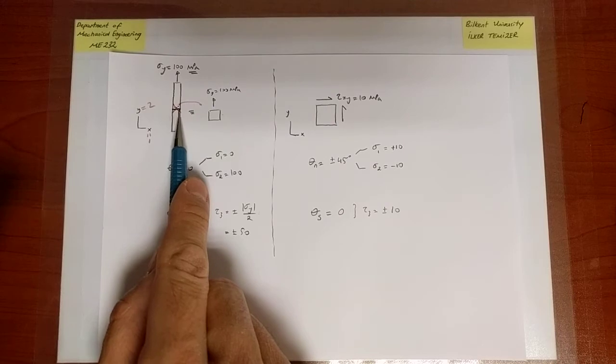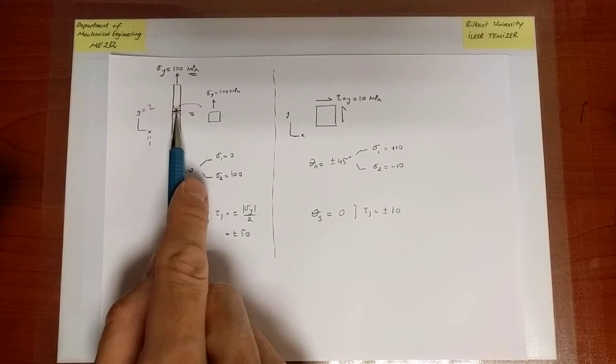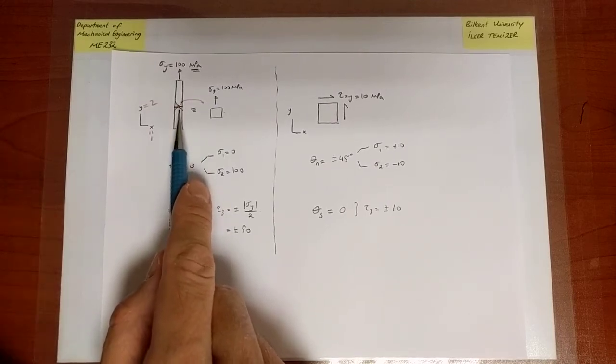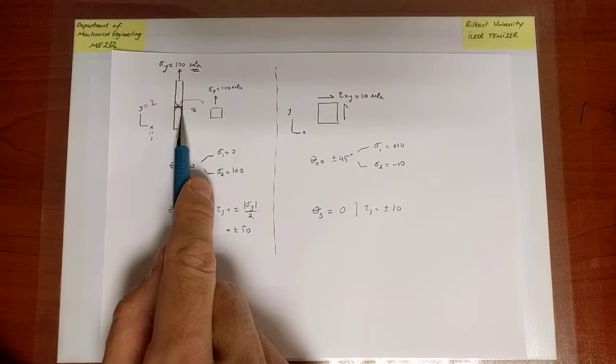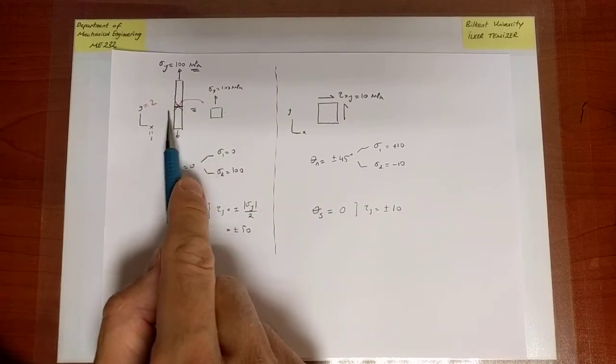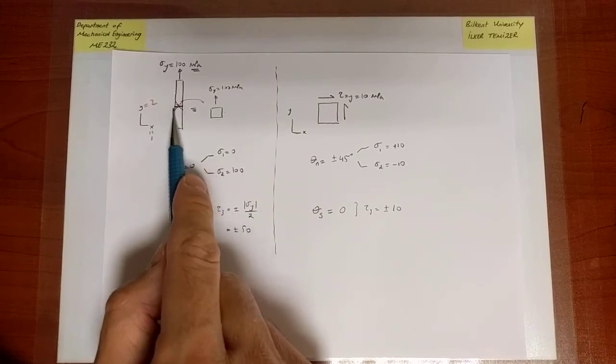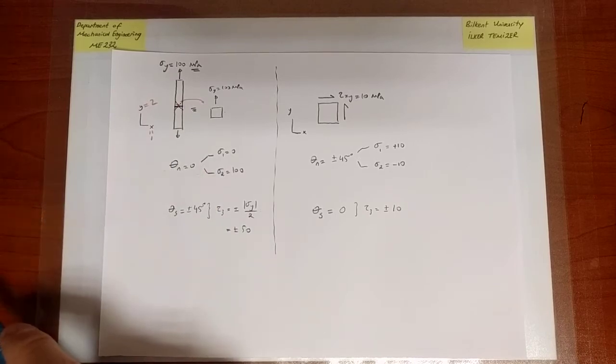That's this blue line here, already the direction perpendicular to the direction of loading. I've already given you an example: what we expect with a brittle material like glass is that it fails like this along the blue line. On the other hand, a material like metal usually fails across one of these red lines, or those lines are indicative of its failure regions.